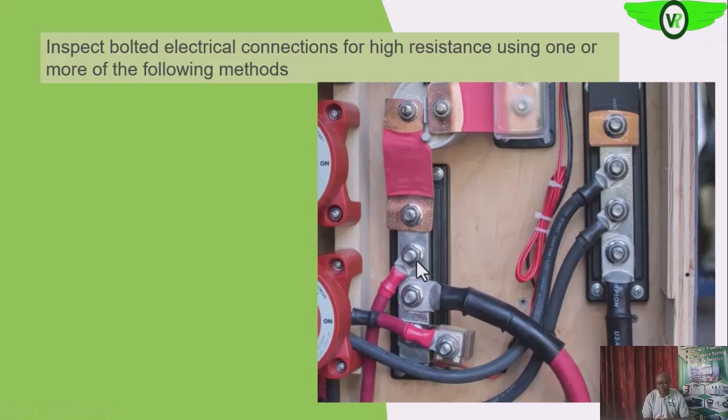So what we need to do is to clean up and retighten the bolt. We'll see how to determine the torque level later. The normal torque level is dependent on the size and the grade of the bolt.